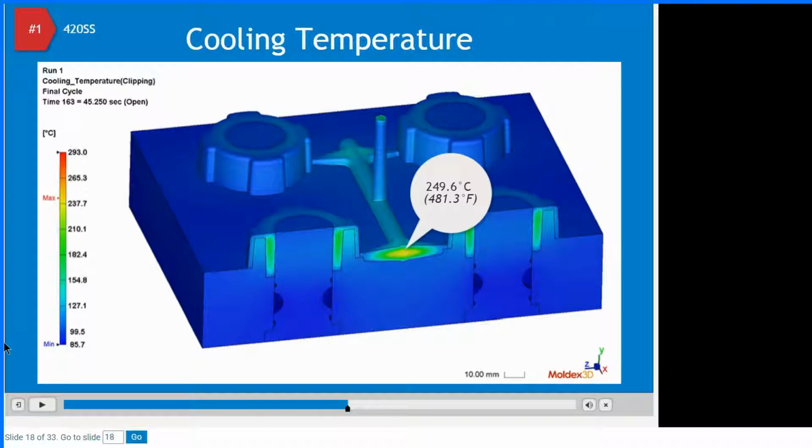How well is this mold designed in regards to placing water lines and addressing these temperature challenges in the mold? Right in here, you can really see in a cross section, this is the ring circuit. The ring circuit of the water goes from here around the insert and back to the next insert. And when we watched this movie, we saw the material coming in and these cores getting pretty hot.